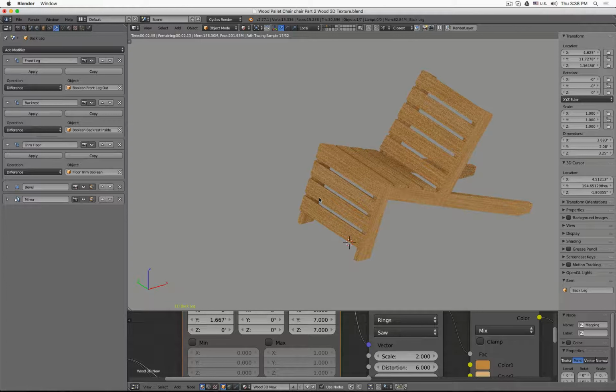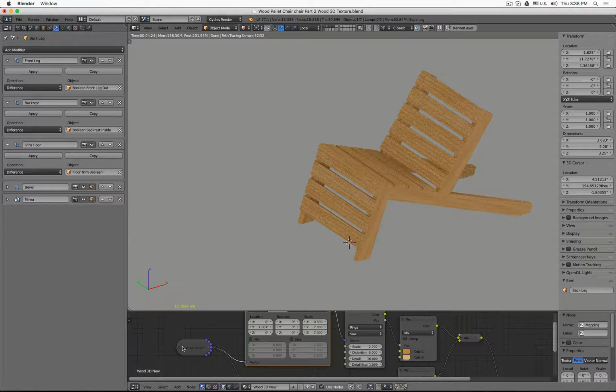and because the texture is actually using the object's orientation, you see now it also flows with the rotation value of our object. So we don't have to deal with a material that only goes strictly along the x-axis. The material, because we used this object as a texture coordinate, uses the local x orientation of our object. So we can always rotate it, and you see the material updates.